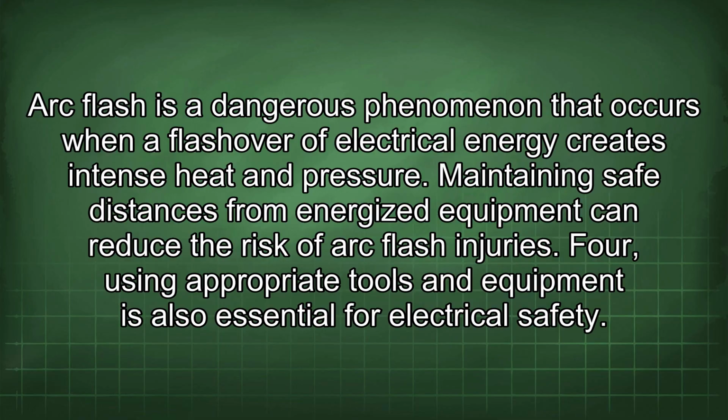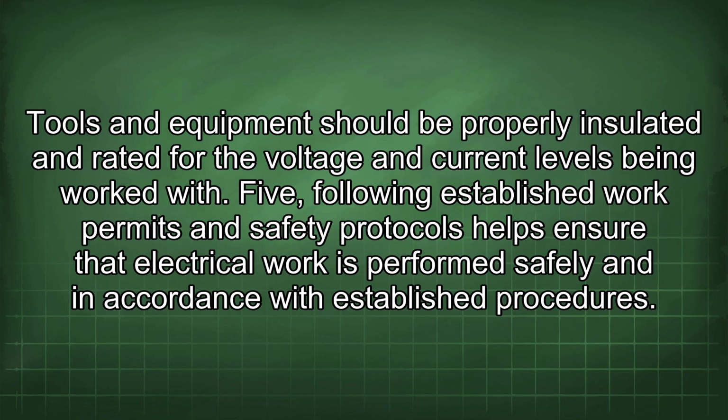Arc flash is a dangerous phenomenon that occurs when a flashover of electrical energy creates intense heat and pressure. Maintaining safe distances from energized equipment can reduce the risk of arc flash injuries. 4. Using appropriate tools and equipment is also essential for electrical safety. Tools and equipment should be properly insulated and rated for the voltage and current levels being worked with.